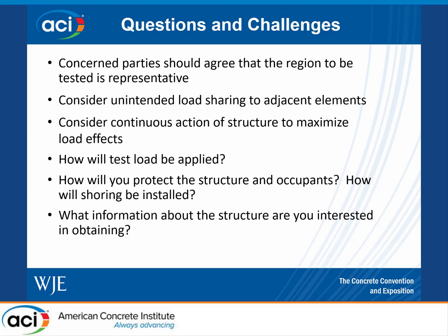That involves shoring, typically, that we'll talk about further later, and you need to consider how that shoring is going to be installed. In many cases, the shoring itself can be a significant portion of the load test. And then also, you want to consider what other information about the structure you are interested in obtaining in addition to the deflection measurements.